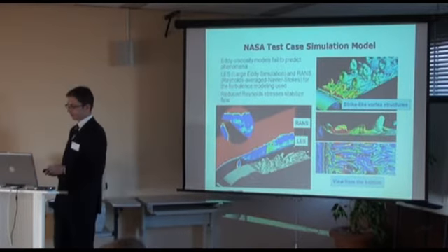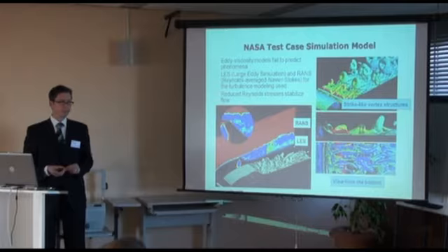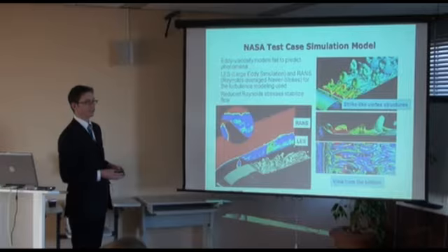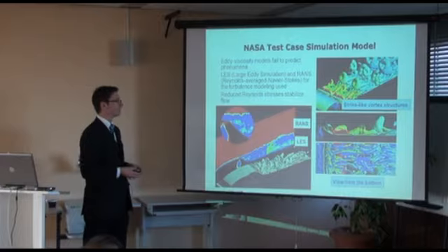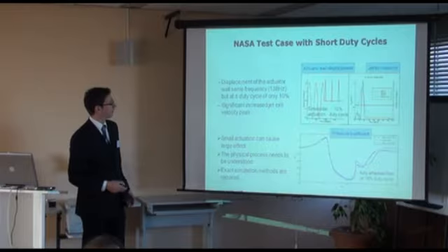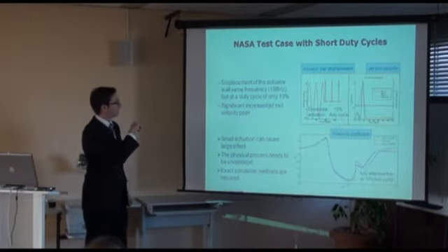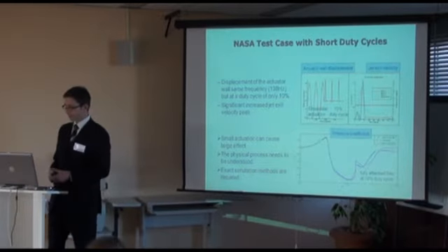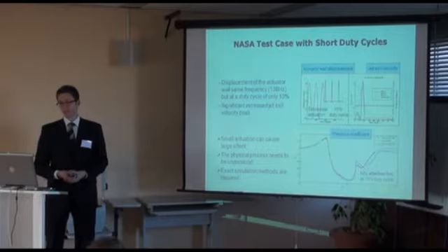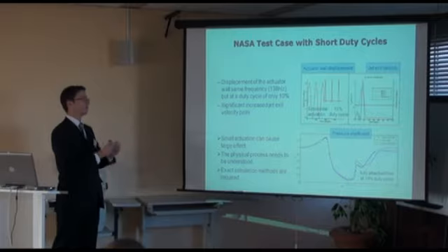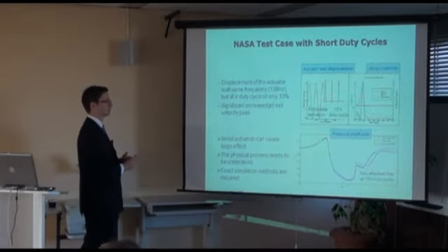The point why I'm showing that here is that once you are able to predict this flow, really to simulate it, you're also able to predict what your active control does. And you're able to predict where you have got to manipulate the flow to improve the overall situation. And this is shown here. So they optimized the jet coming out of this bump. And the colleagues here showed that by having only a duty cycle of 10%, so having only 10% of actuation, it was possible to get almost the same effect.